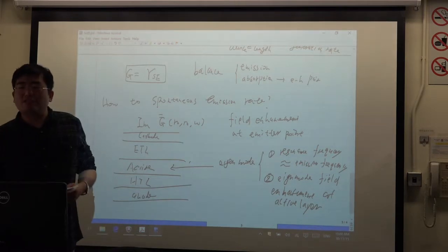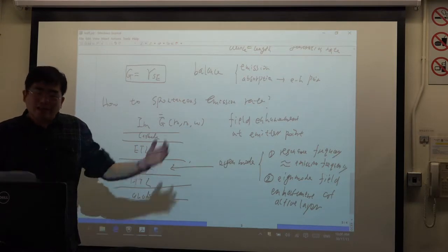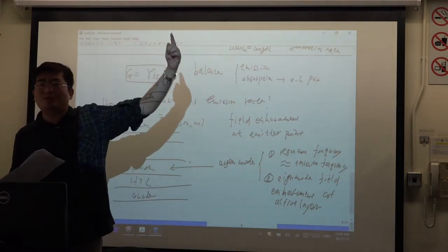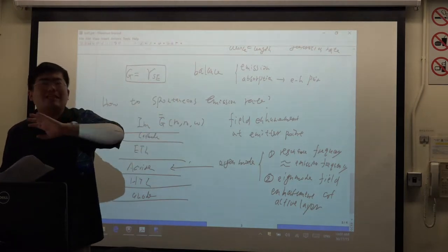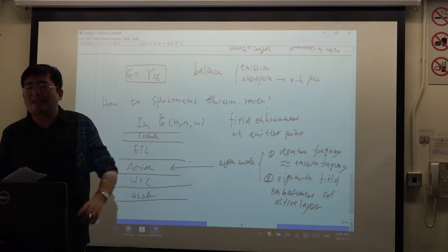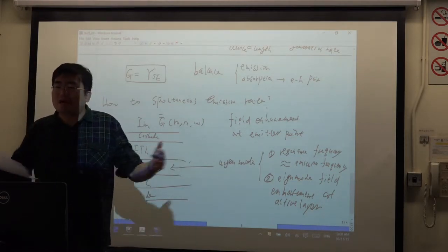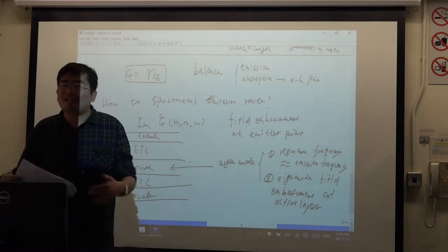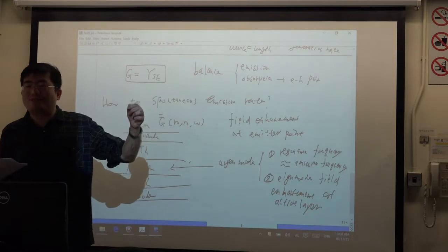Okay, the emission and absorption are balanced at thermal equilibrium. And non-thermal equilibrium just has an exponential increase by the Boltzmann statistics. This physics is so universal in all the semiconductor devices. Thermal equilibrium balance, generation-recombination balance, some kind of balance, emission and absorption balance. And non-equilibrium is an exponential increase.